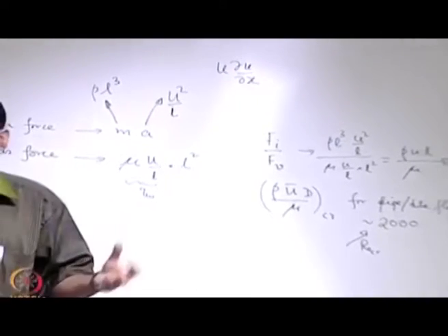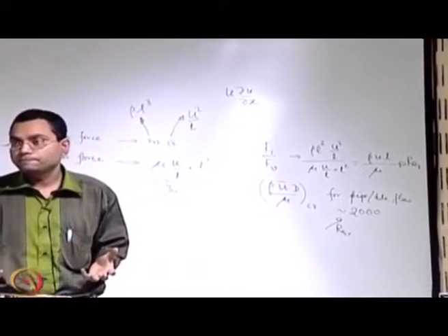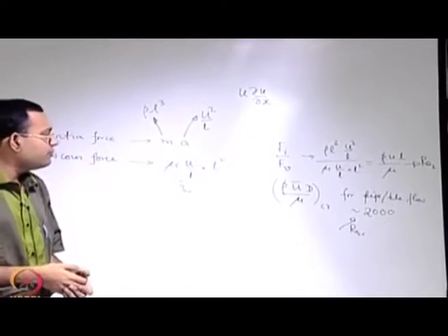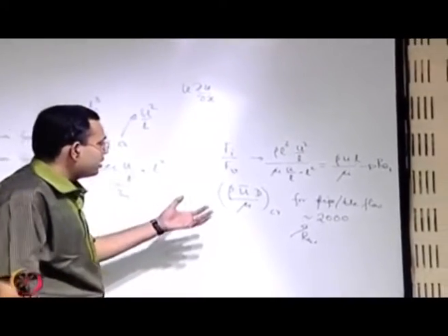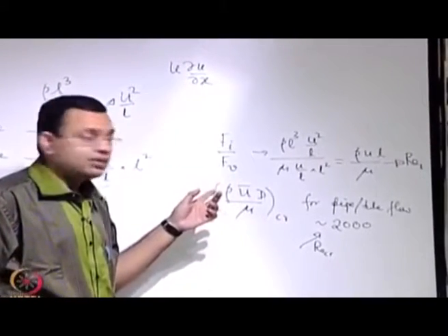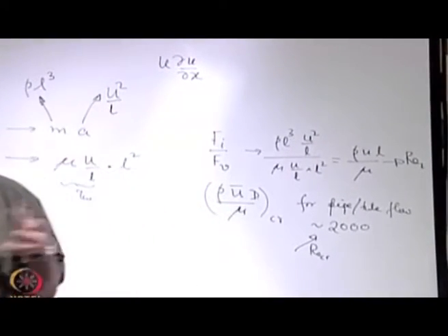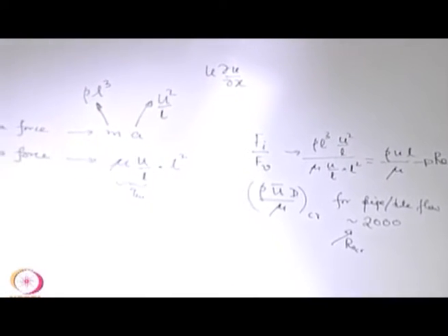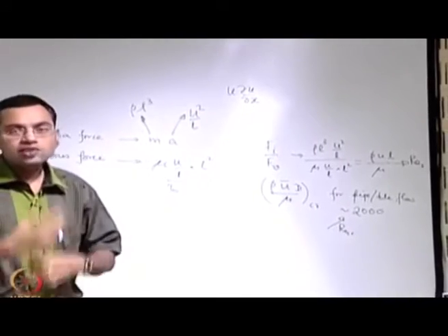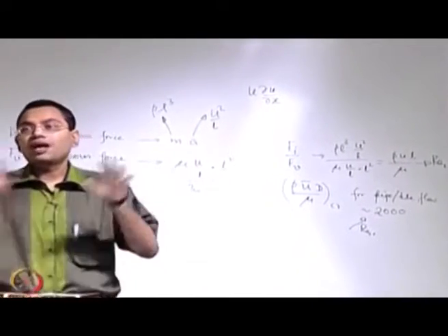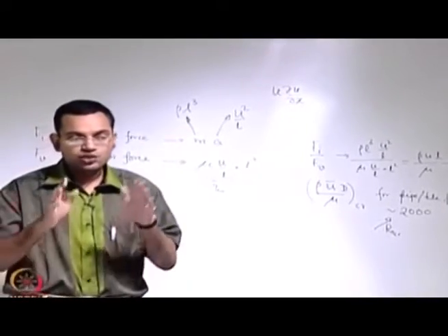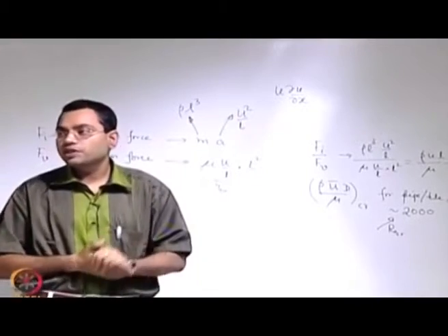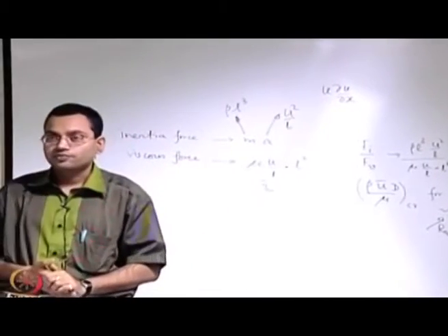Then the perturbation cannot grow in amplitude at a particular point and it sort of gets destabilized. On the other hand, if you have a high Reynolds number flow, then the inertia forces are important, and when you have perturbations, the perturbations will try to get amplified, and because of the amplification of the perturbation you have these types of situations. So these two qualitative pictures are hallmarks or representatives of laminar flow and turbulent flow.